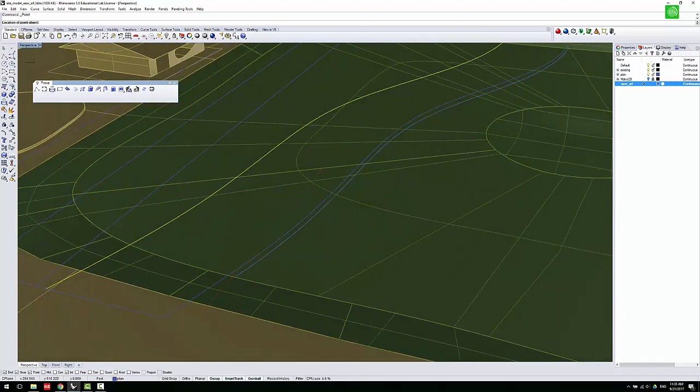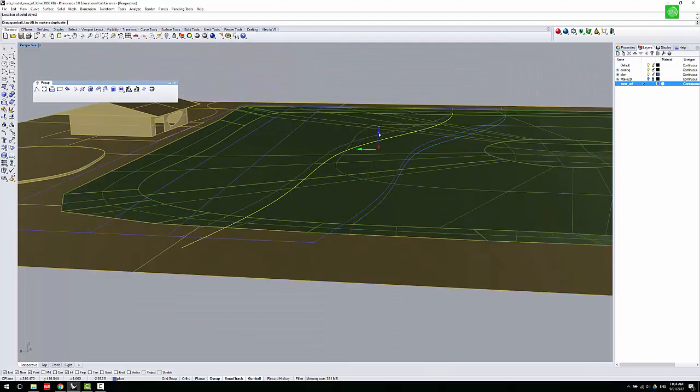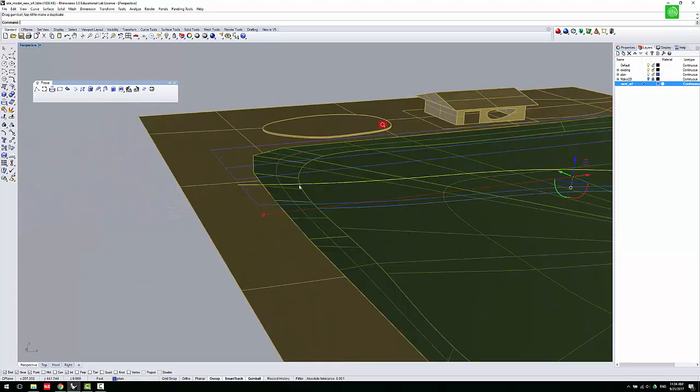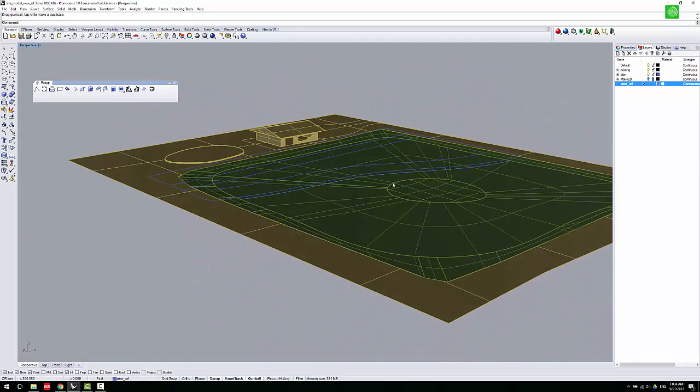And for this one, because of the step, you can use the point tool to check the elevation. Right now it's 0, and here it's like -2. So I just want to make this go down. Let's make it -1.5. Hit enter and release. So these lines go down.